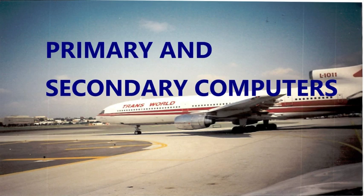If you've taken an A320 course, some of the terminology is a little confusing, because there may be a reference to your SECs, short for spoiler elevator computers, or secondary, which is kind of funny because your elevators are actually part of the primary flight controls, not secondary flight control systems. So again, a little confusing, but just understand that when it comes to the A350, they are identifying the computers by name.